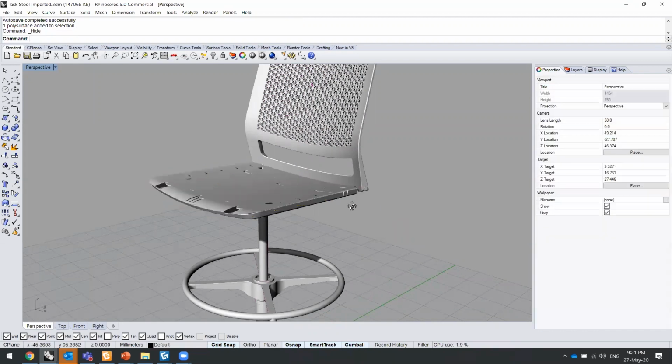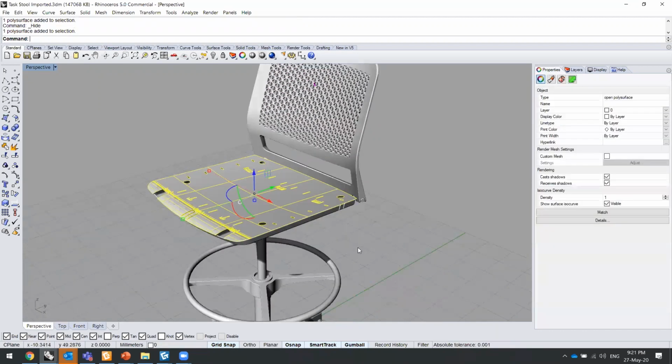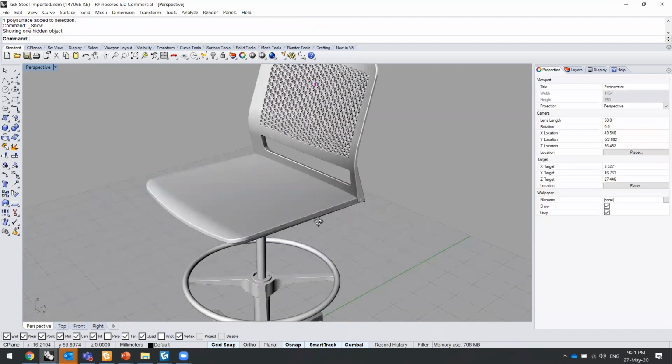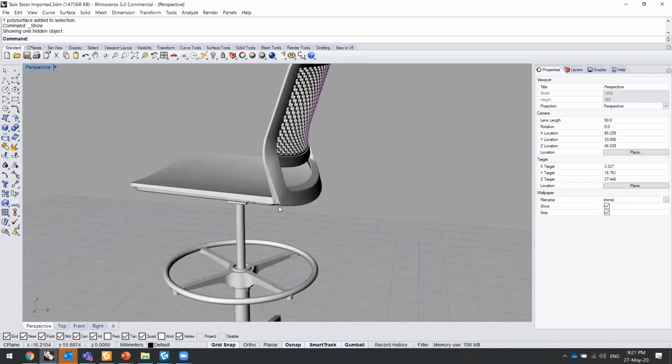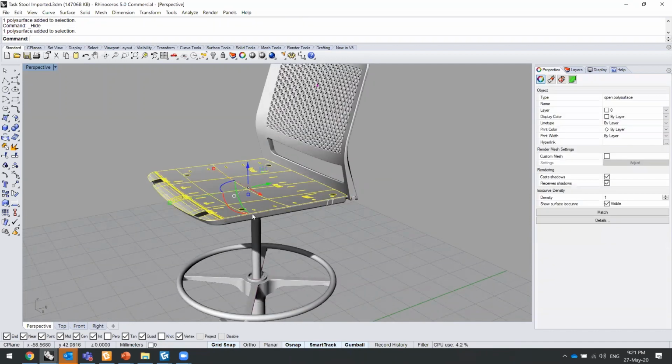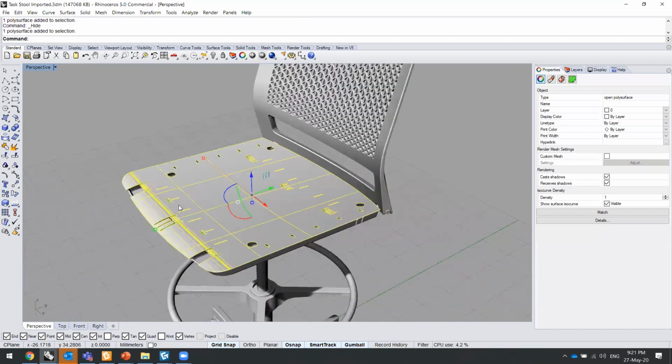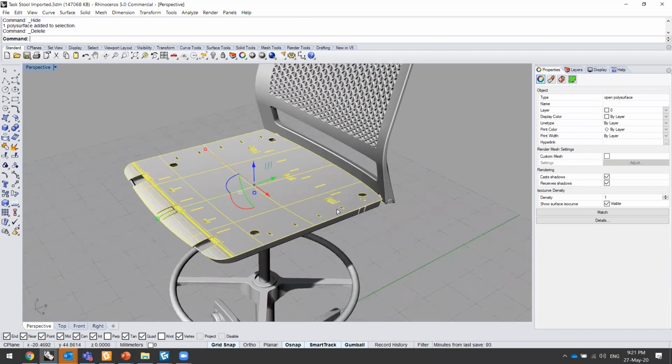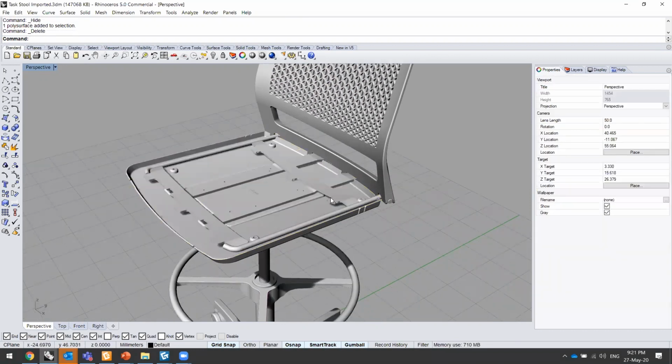So right underneath the seat, there are parts like this with a lot of features. And if I show everything over here, there's something you don't even see. So that's something you want to remove. And this alone can be a few thousand polygons based on the details that we have here. So just delete it before even putting it in CT.